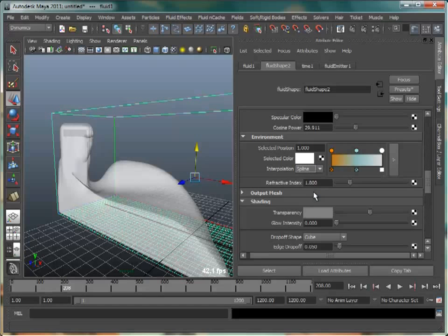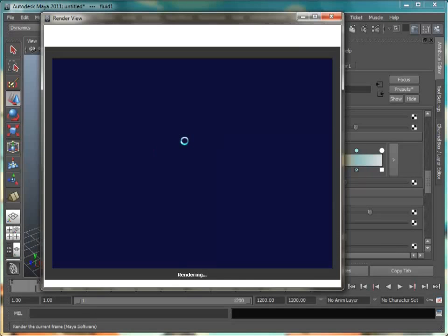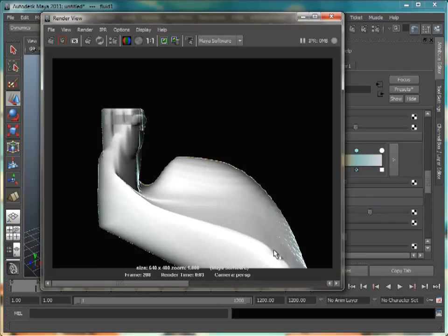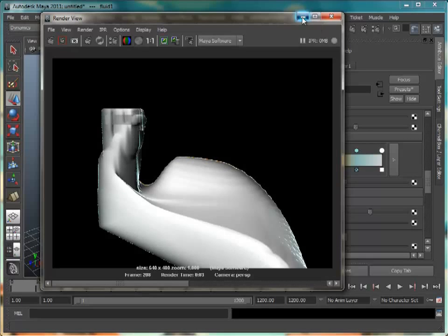And if it is spline, then the values are interpolated with a spline curve, and it takes the neighboring position markers into account for a smoother transition. Okay, so you have that option there, and refractive index controls the refractive index of our environment. So if I go ahead and render, you can see that that color will be reflected in this fluid.